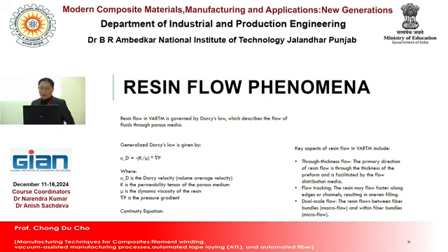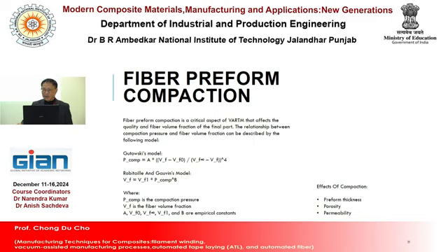About fiber preform compaction, we use two different models, which are very famous in this field, the Gutowski model and another one. These two models are usually used inside computational programs. The effect of compaction concerns the preform thickness, porosity, and permeability.